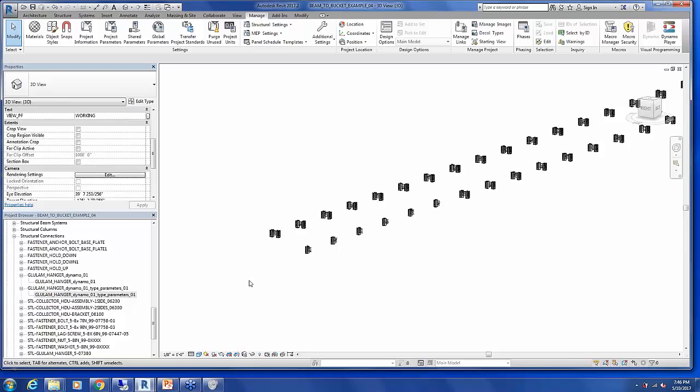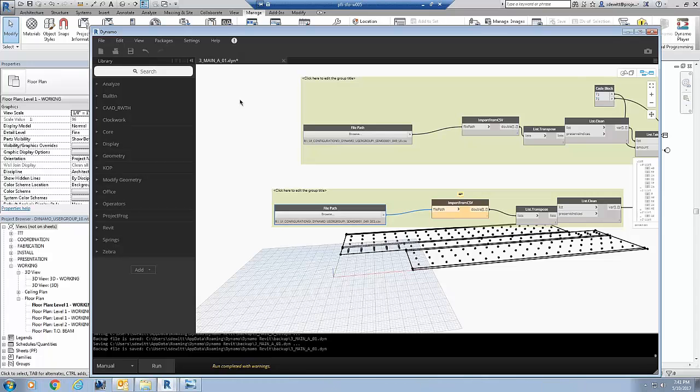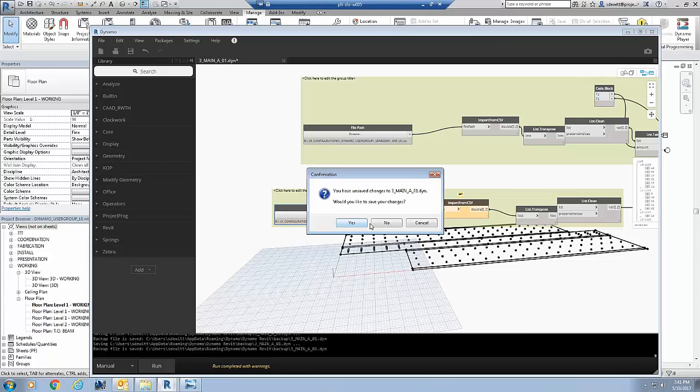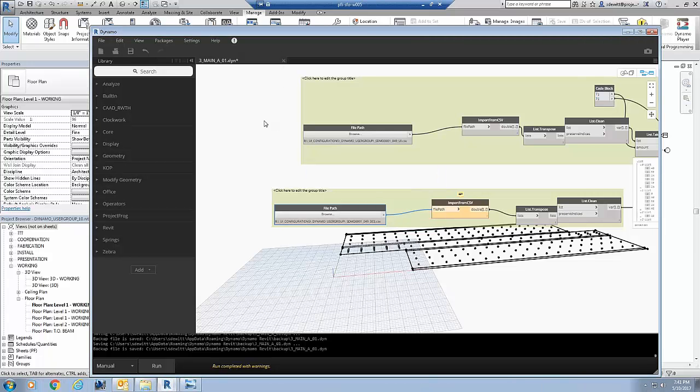That's one thing that's kind of cool about it. If they're driven off the same shared parameters, you're just matching shared parameters. If this shared parameter exists and it's yes, and this shared parameter exists and it's yes, then replace with this family, right? So you're not having to isolate elements and pick things. It's just finding the same data and then moving it to a type parameter. And this one's probably done. It is. All right, and we'll run our last one, and then I'll stop boring you with that.